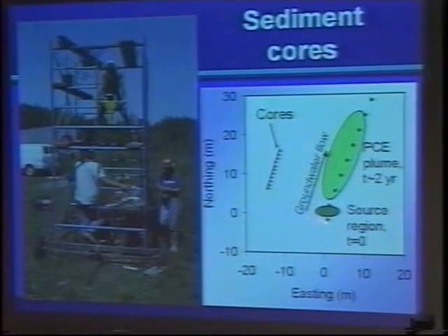Now, my former advisor has done experiments here subsequently, and there are many other chemicals that now exist in this region of the groundwater system, and we didn't want to study the geochemistry of that, so we marched over here to a clean zone of the aquifer and collected 11 cores covering 10 meters of the aquifer at the same vertical depth that the original contaminant tracer experiment was conducted. That's about 1.5 meters to 3 meters below the groundwater surface, or between the ground surface, about 0.5 meter below the water table.